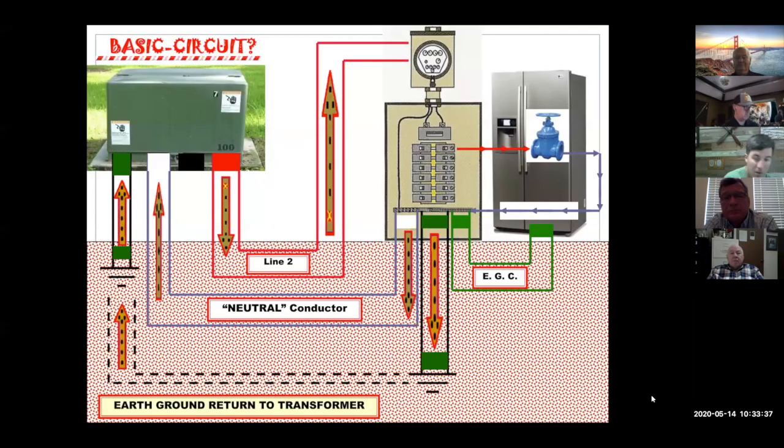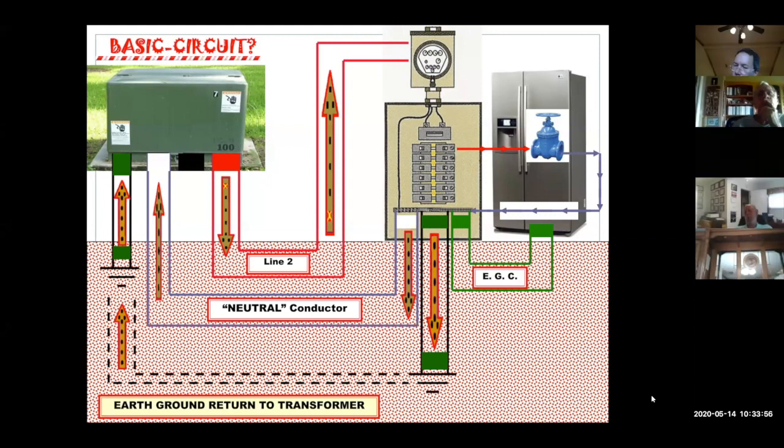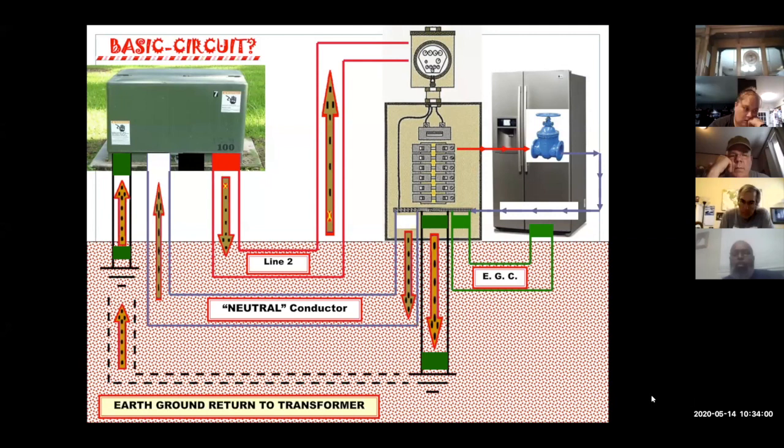Emphasize right now, the ground is the most important thing you have on a service. And you know how bad grounds are. The ground rod is bad, the clamp is bad, and all of that. I'm going to tell you, if you've got a low impedance ground, you're going to save your service. Surges and all kinds of things will be prevented by having a low resistance.